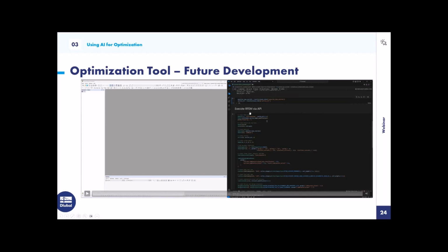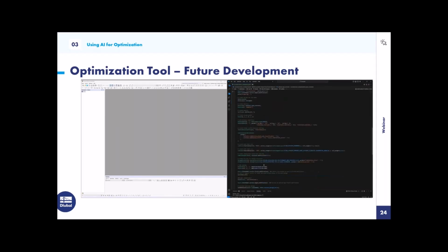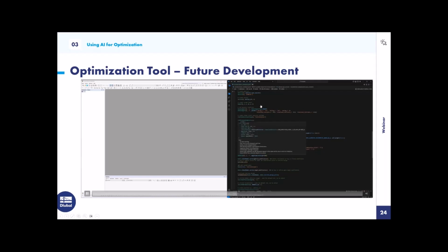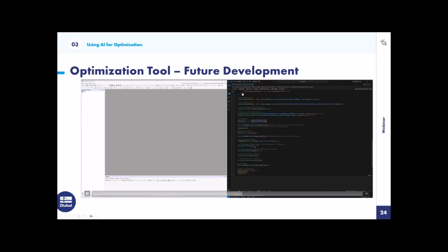With that material and section choice, we go and compute the FEM model, because in the end, I think we want to show that this AI prediction really holds true what we have requested, and we need to prove to maybe a checking engineer or so that these results are correct, and we want to have maybe the FEM protocol. So what we do here is set up this analysis again, as we did with the introductory video, define the section, the loads, and compute that, and do the concrete analysis here. Yeah, and in a second, you will see that script running.